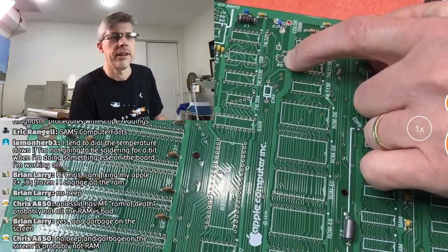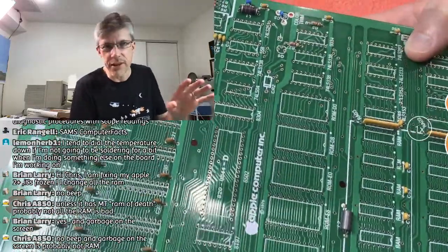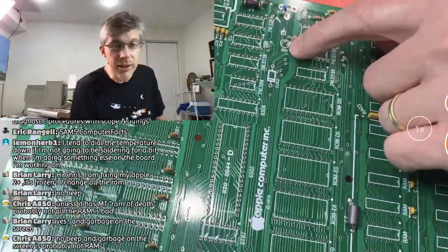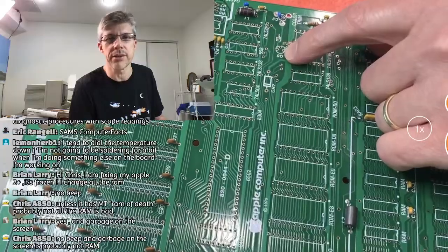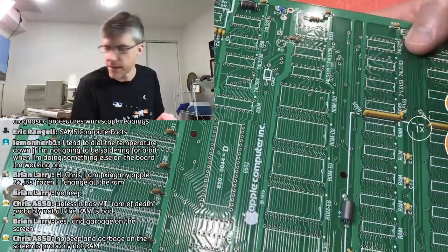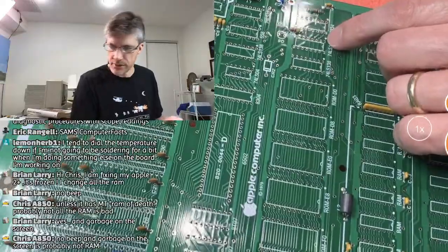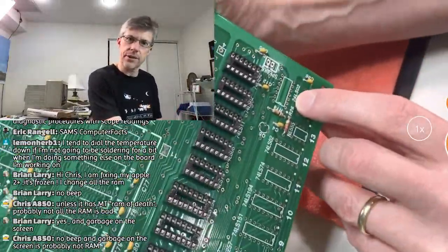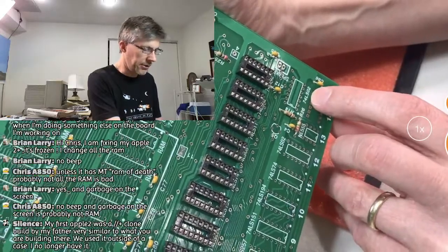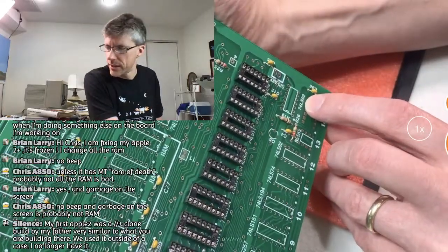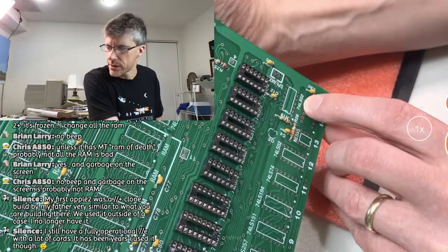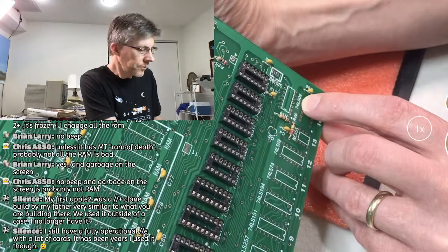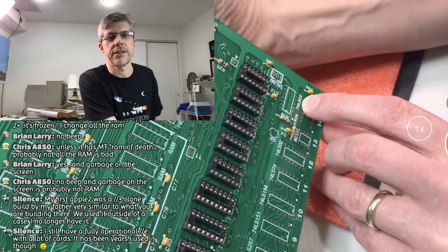Then text wouldn't have the color fringes around it, and when you went to graphics mode, it would turn the color back on. That worked okay, but you'd still get some bleed through. So they added a whole other chip down at A14, I believe. Yeah, this one right here, this LS02. They added this chip later on, according to my notes around revision 7, and that actually solved the problem.